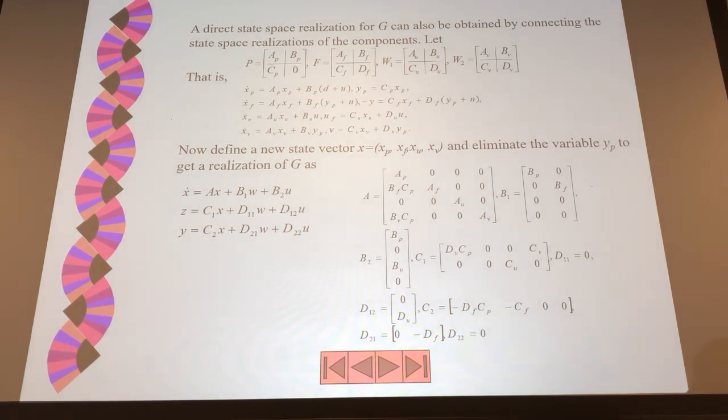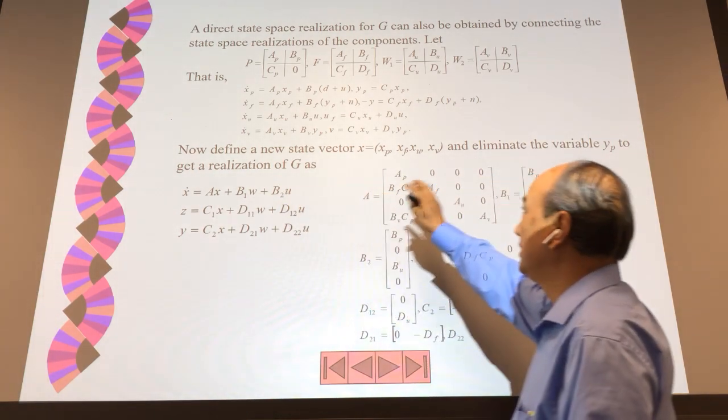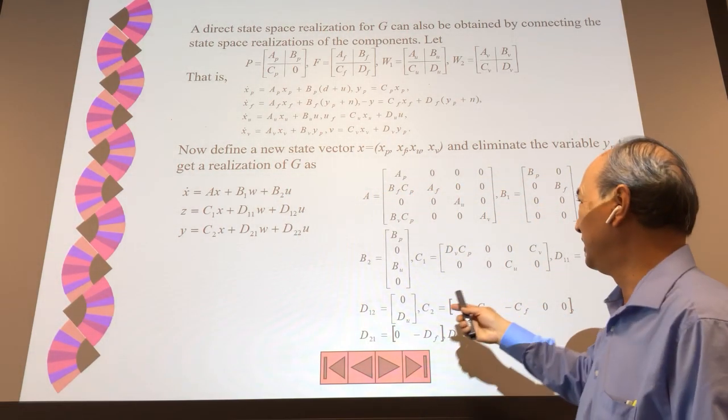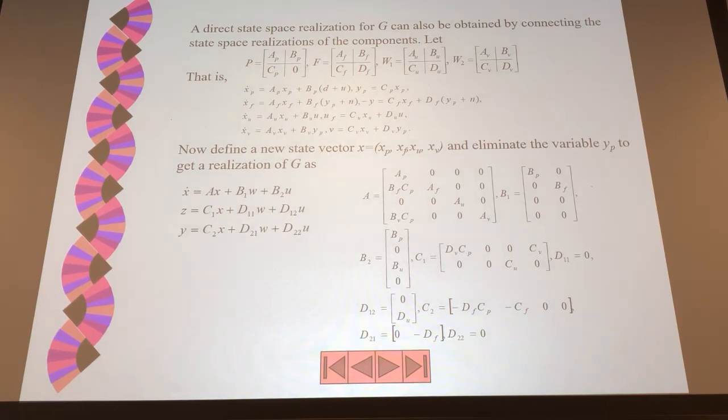But it means that Y should be stable if we ensure that the transfer function between Y and Z is working properly. For stability, this related interconnection, I think the stability is related to this A matrix. And the stability, of course, is influenced by the feedback in here. So we haven't discussed how to design a U yet. U is the only thing that you can change. U equals something called state feedback or output feedback or dynamic feedback. That's yet to be designed. We don't discuss this one yet.